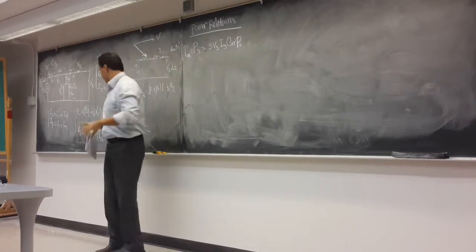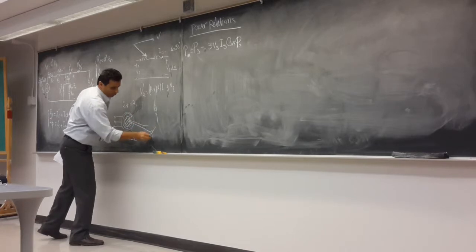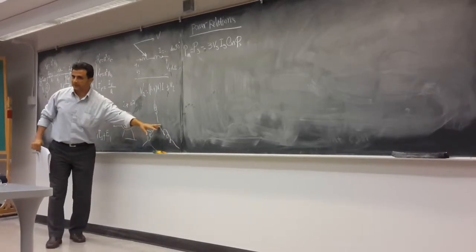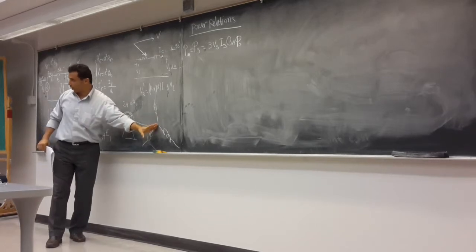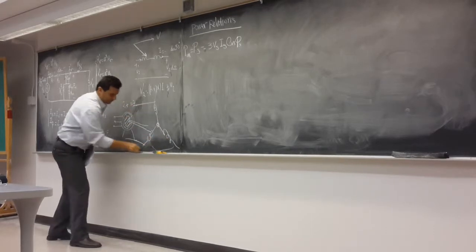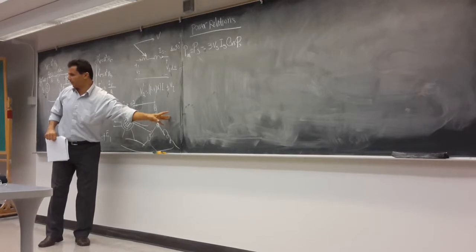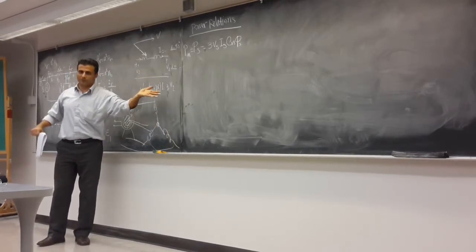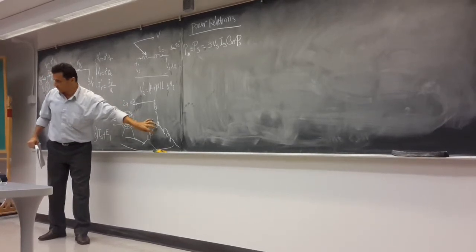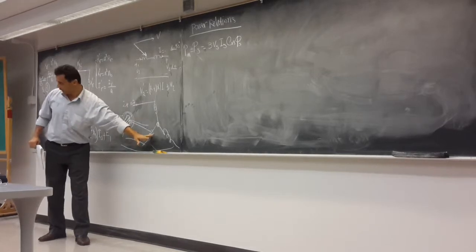If the motor is connected, on the stator side, see, there are three windings. This is the stator winding. We have three windings in the stator, phase A, phase B, phase C. They can be connected as a star, like this, right? Or they can be connected as a delta. Nobody connects as a delta, always a star. But if in the problem we say this is delta connected, it's delta connected. So the stator of an induction machine, if we don't say anything, is star connected, right?